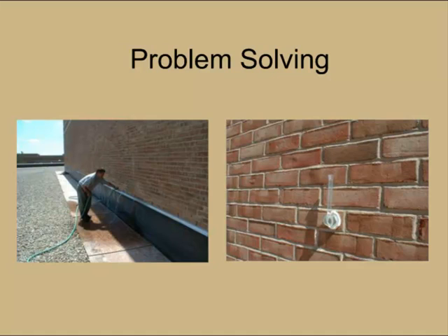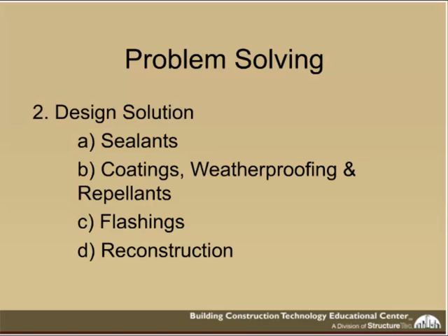Very, very effective testing. On the right, that's a Rilem tube. What you're doing there is filling that tube with water, and you're monitoring the rate of absorption through the masonry and the mortar joints. It really tells you how porous these bricks really are.